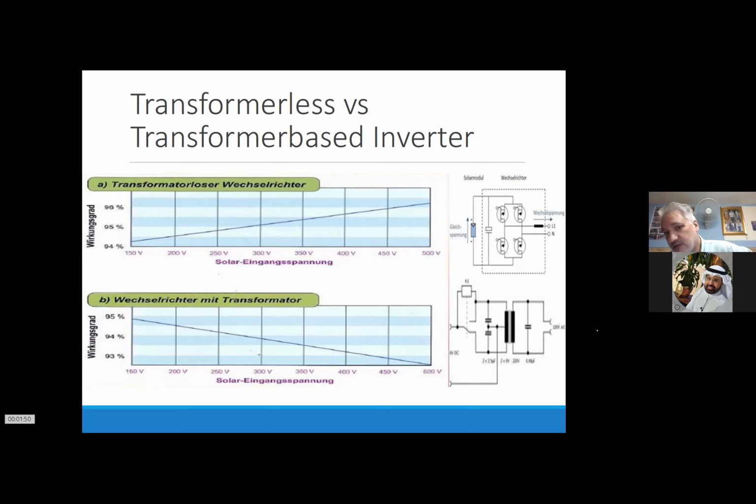So the derating is always based on the voltage you give it. Like I said, if you lose 100 volt and the margin is 16 or 18 modules only, add 2 more modules, so you go towards 18 or 20 modules. That means with 20 modules, you almost hit 1000 volt. The possibility that you are at 600-700 volt, even in summertime, is much bigger.